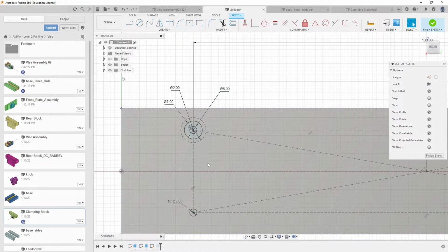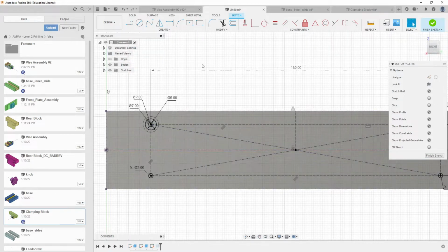Hold on a second. I'm going to pause, and I'm going to go measure the inserts. Okay, so the inserts are 5.5 in diameter, so I'm going to make this 5 because it'll allow for material to melt into the threads, if you want to call them that. Then when we get done, we'll add a chamfer to this.